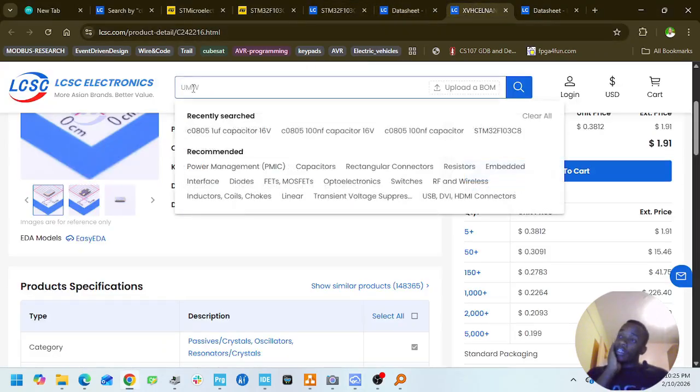So it's an industrial instrument, and we want that LED to be exposed to the user. Because there's a casing around the device, there are two things you can do. You can have a through hole LED that has long legs that protrude rather close to the casing, so that you just see the LED itself, or you can have a surface mount LED and then add translucent LED guides.